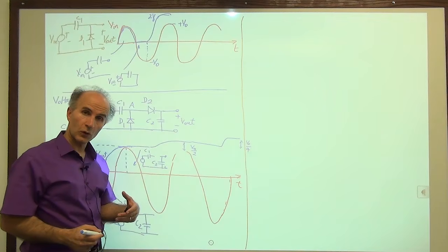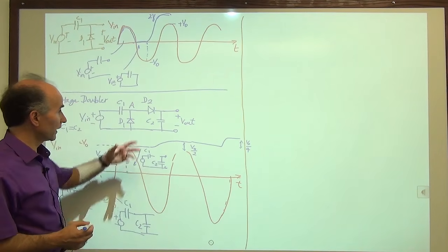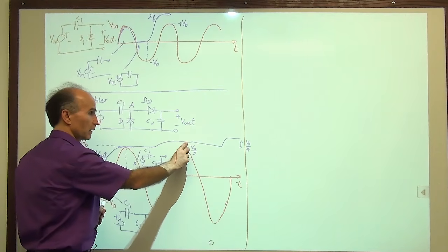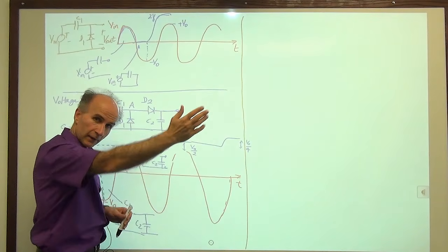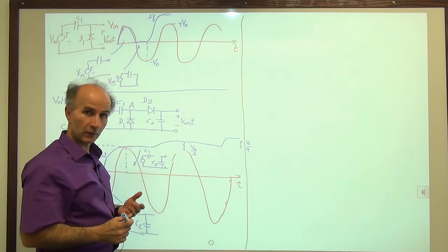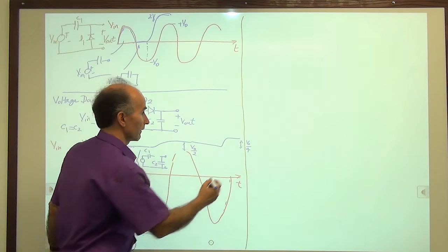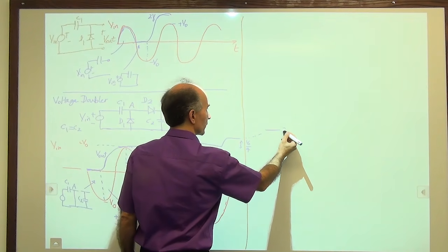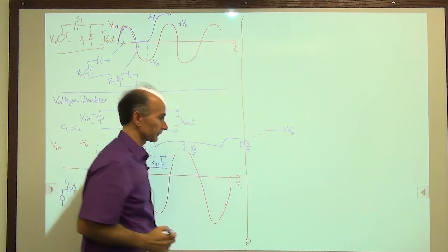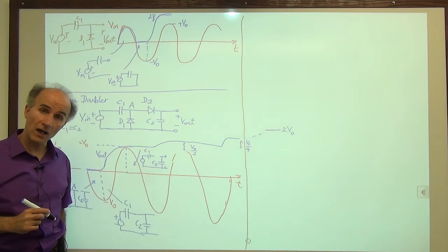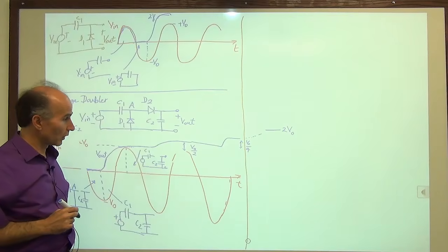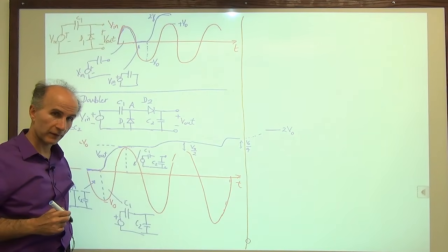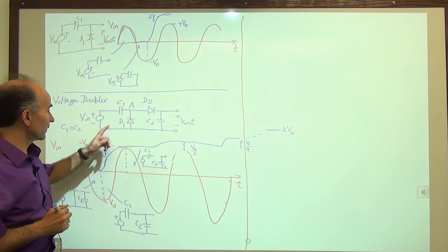and so on. So the final value of the output voltage, the voltage across the capacitor, will be V0 plus V0 over 2 plus V0 over 4 plus V0 over 8, etc. And if you expand that, of course, we know that's equal to 2V0. So eventually, if you wait some cycles, this approximately becomes equal to 2V0. And then it stays constant, or asymptotically approaches 2V0, and it's just approximately equal to 2V0 forever.